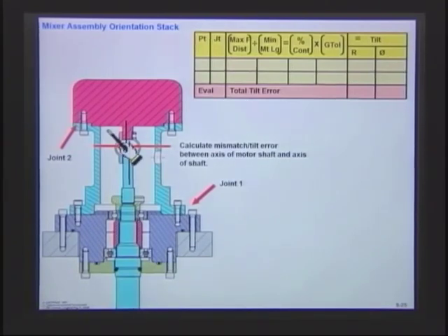We have two joints. Remember our datum? Our datum on this part was the axis, and then I think we had a secondary datum here. So our shaft is standing up here like that. I'm going to negate any of the tolerance on the bearings. Remember, the clearance on the bearings I think was 4/10 for one and 1,000 for the other, so there wasn't much. I suppose we could add that in also, over that distance, and you can maybe take a look at that a little bit later. But if this is a rotating part, it's probably going to be on center, so I didn't include any of the tolerance in the bearings in this calculation.